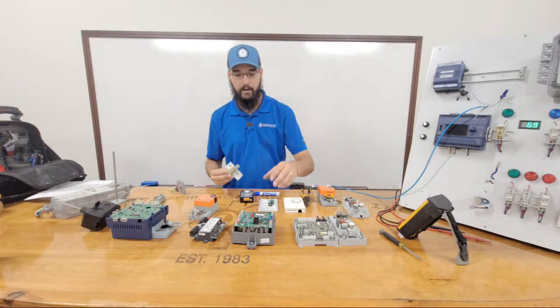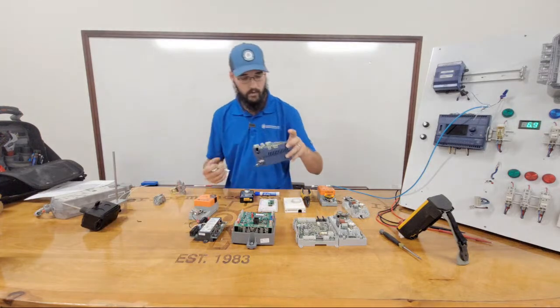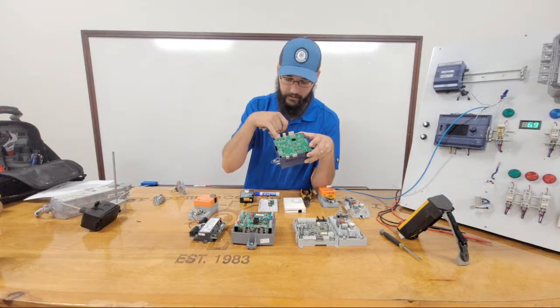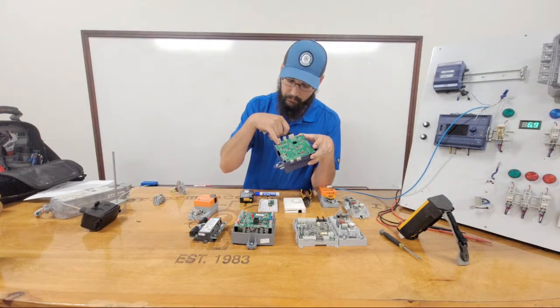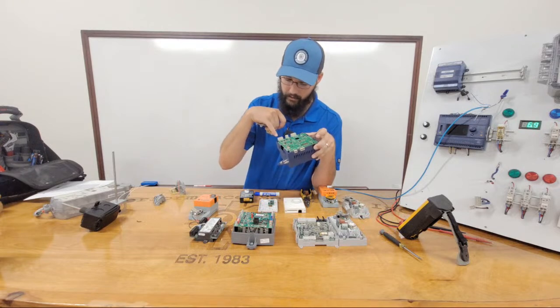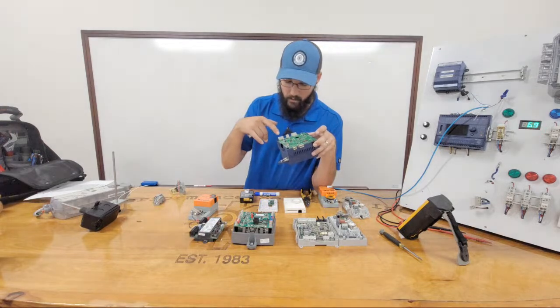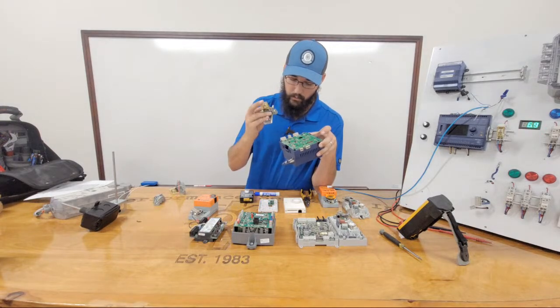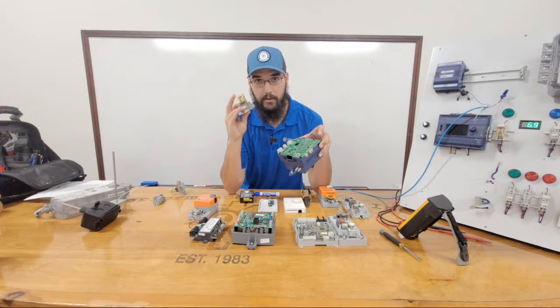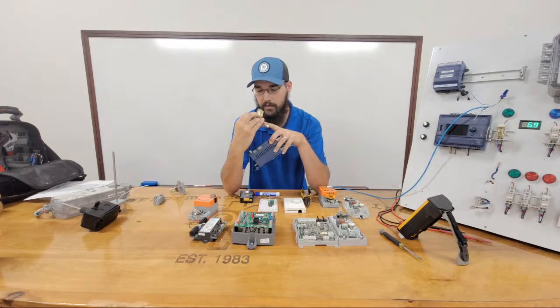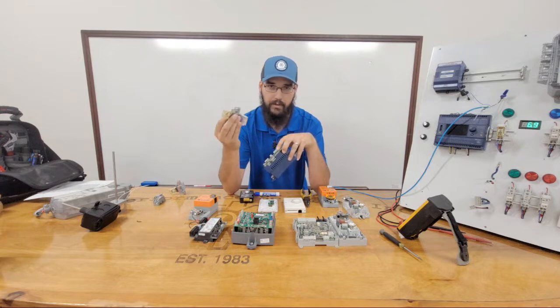Ultimately, on your binary outputs, for example, they're going to process through these triacs right here. So this is a Distech. These little black boxes right here are going to be your triacs coming to this output here. And it's actually numbered. You have DO1, 2, and 3. So these need to be feeding the coil voltage right here, which is, on this particular one, 14, 13, pretty standard numbers.